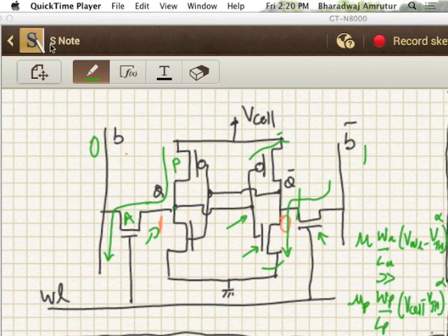So you will lose, yes, your whole noise margin will come down, right? But you have to consider all of those factors of area, noise margin, and so on. Usually PMOS of minimum size kind of works well. And so typically you will have PMOS and access device minimum size, and then the driver device to be maybe 2 or 3 times bigger depending on the